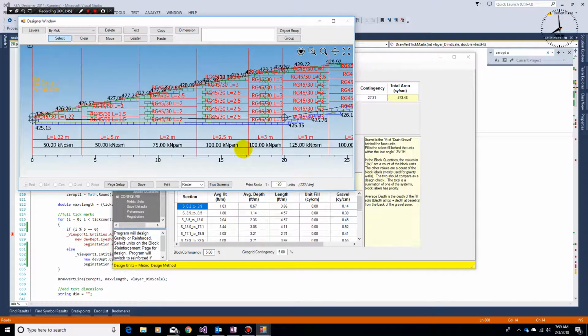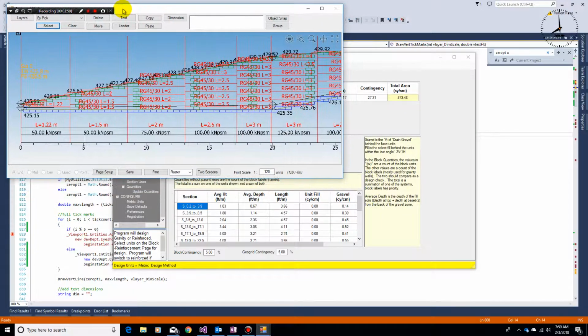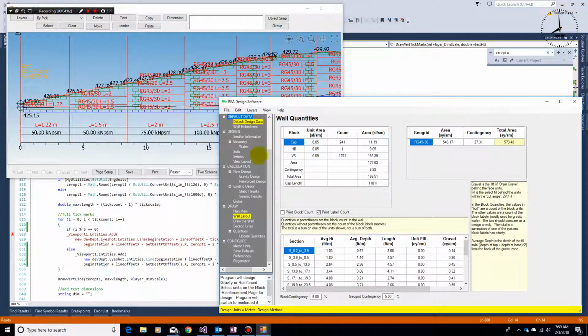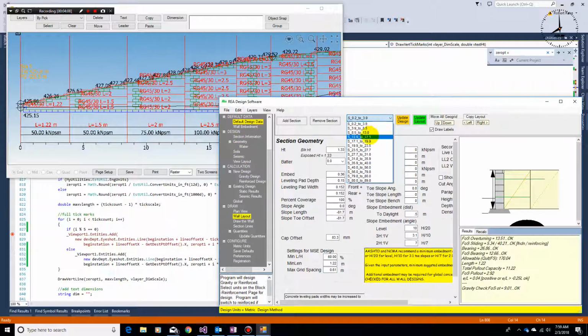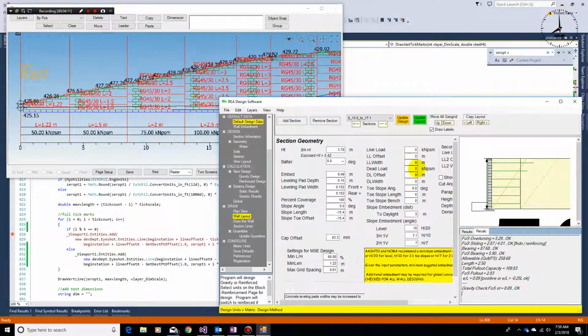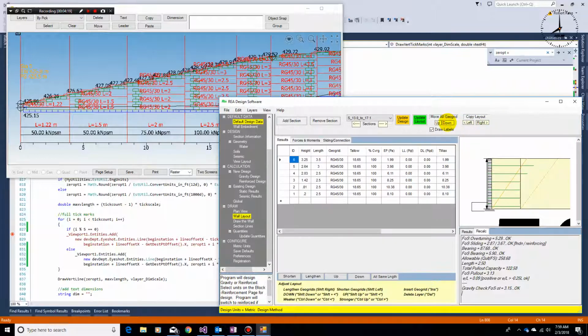Also, when we get into looking at the wall, we can see, well, our grids don't line up going across here. This is something else that I always clean up. So if I come in here at, this looks like about 13 meters. Let me put that up there. Let me put this down here. I'll go to geometry. I'll go to 13 meters. There's my wall elevation, and at 13 meters, if I move my grids down, and I'll click on the down button, I'll update the view.